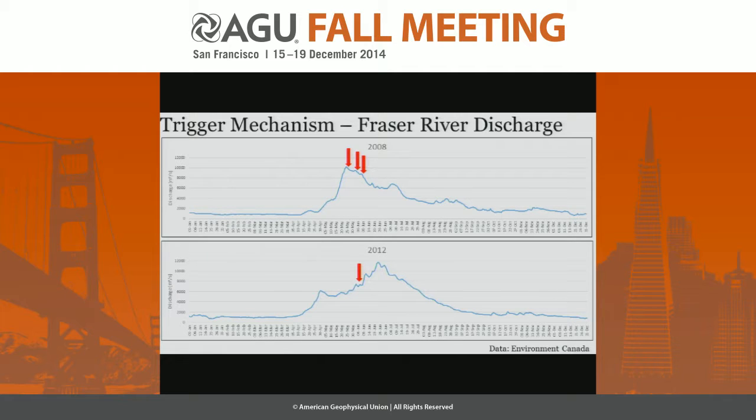And this discharge is during the freshet period, which is caused by snowmelt, and also has large sediment loads because of this. It is noted that while 2012 does not appear at or after the peak discharge, it still occurs after a period of higher discharge. 2012 is a quite odd year in that the peak discharge doesn't occur till late June, whereas usually the peak discharge looks more like 2008.